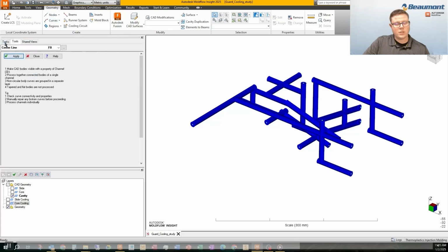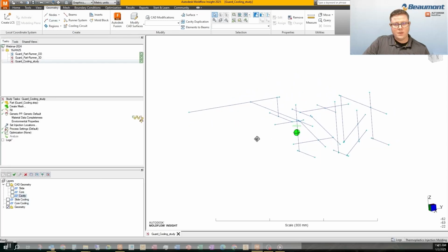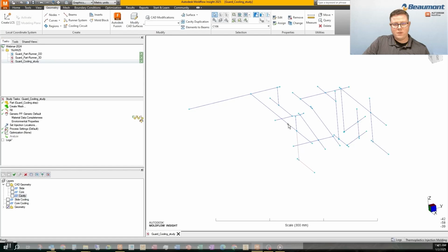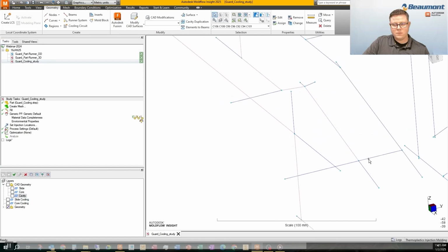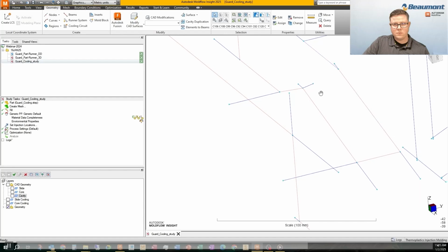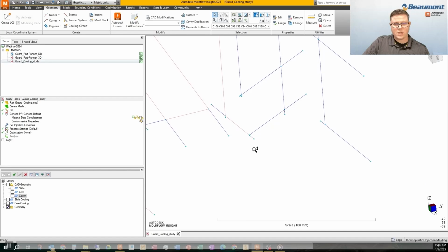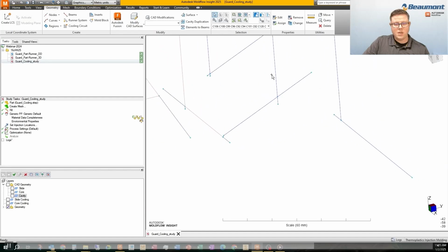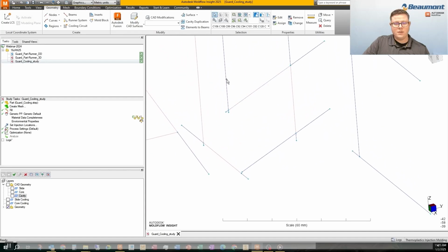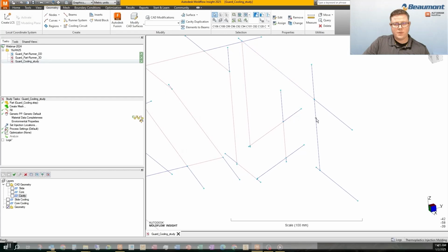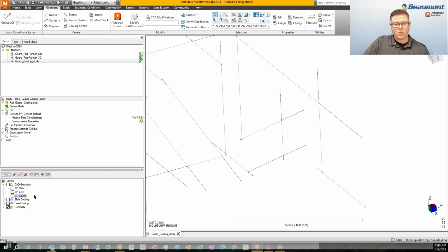Again, using cooling line extraction, selecting that flow path for the water. Now I do notice that there is this real small section here. I'm going to replace that line with a straight line, just connecting the two. I don't want any issues with the simulation.